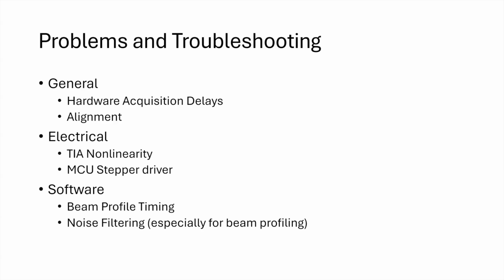And then another problem that we've had was noise filtering with the ADC channel. We've gotten a pretty good fix of it using a lot of filters, so an SG filter, some error function fits, and then we were able to get that pretty much down to a respectable noise level.